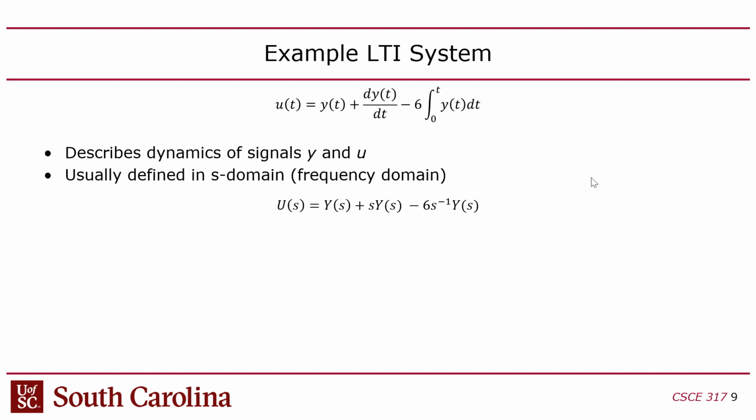And then the integral of Y of t, if we bring that into the Laplace domain, it becomes 1 over S, or S to the -1 power, right? And then that coefficient there, that -6, just comes straight across into the Laplace domain, right? So basically all you have to do when you do the Laplace transform of this is that you capitalize the signal names.